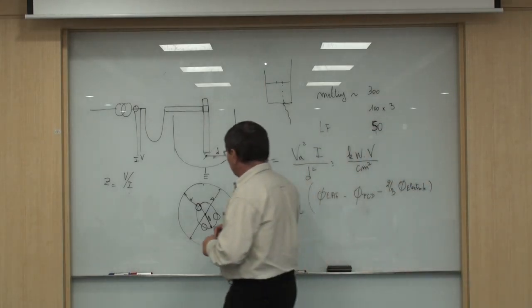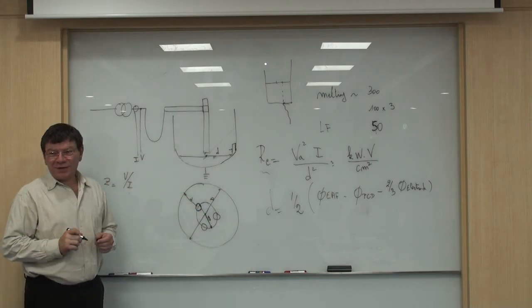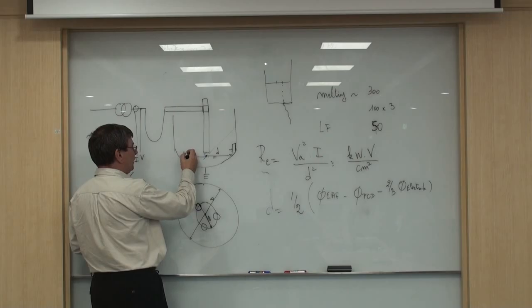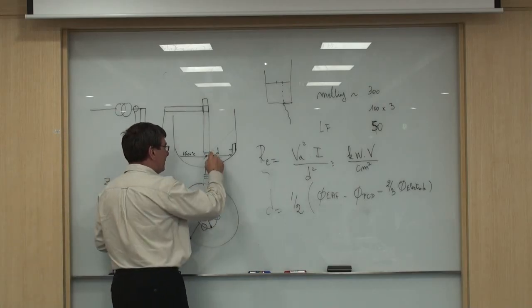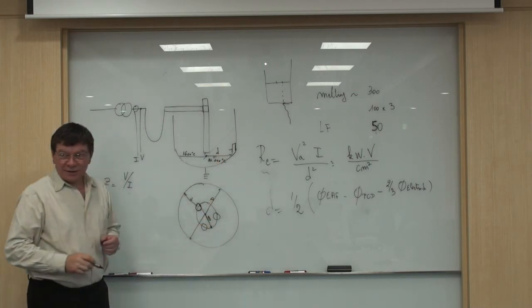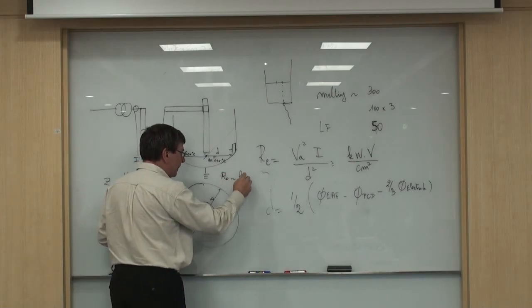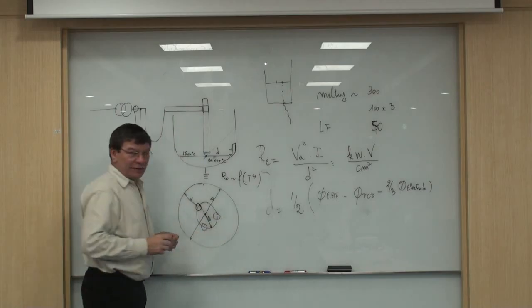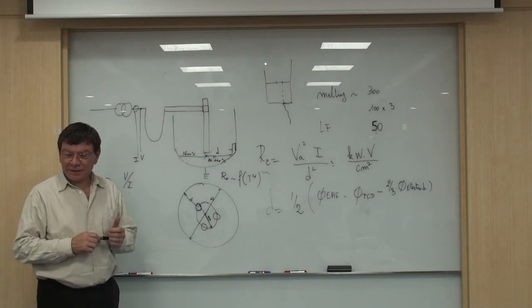You just imagine this surface of the bath radiating with a temperature of, let's say, 16 degrees C, and this arc radiating with 20,000 degrees C, and radiation is proportional to temperature to the power of 4. What is the strongest, you mean? The arc.